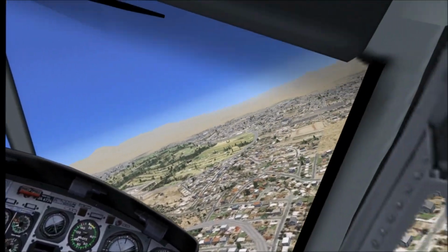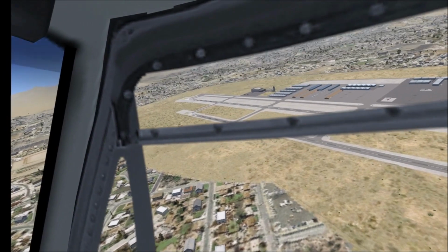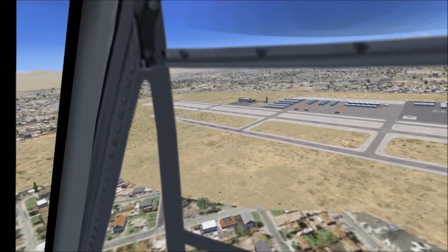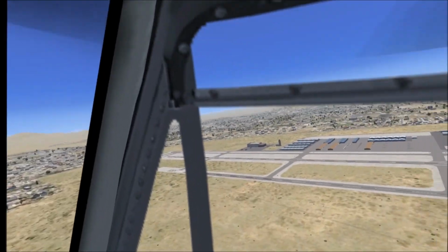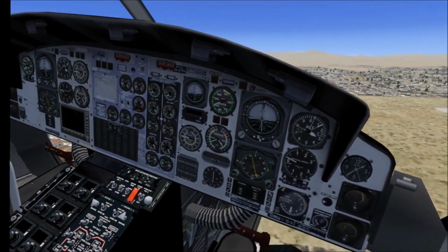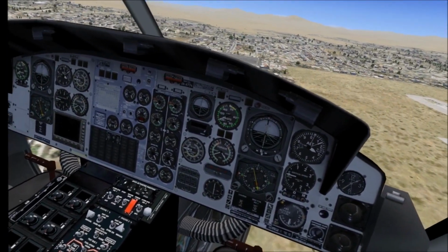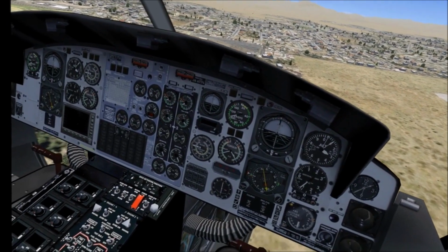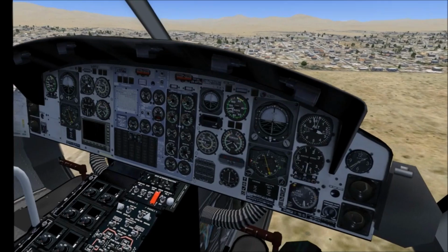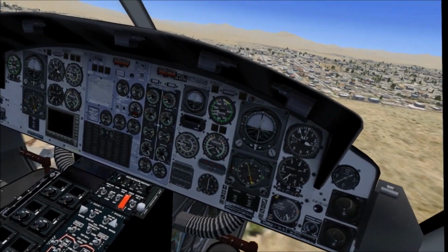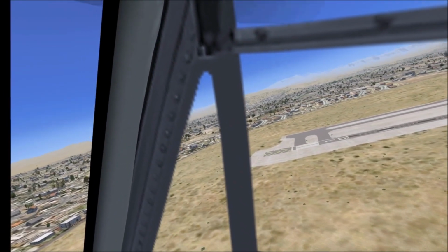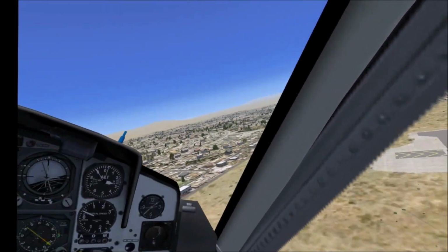Now, here's going to be the challenge, and I'm not sure if we'll be able to do it. So we're going to try it single engine. For single engine, for 70 knots and 58% torque on the engine side of the torque gauge here. For that last test, we were looking at the mast side, or what my manual says is the transmission side. So we'll be looking at a max of 58% at 70 knots, and we'll be looking for 400 feet per minute rate of climb.